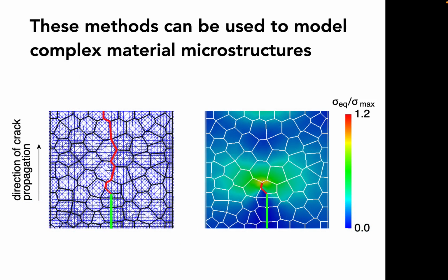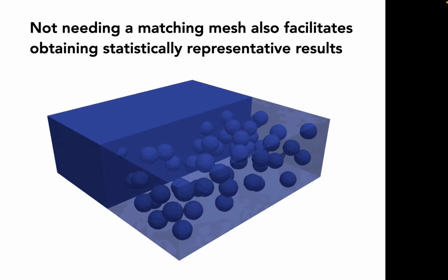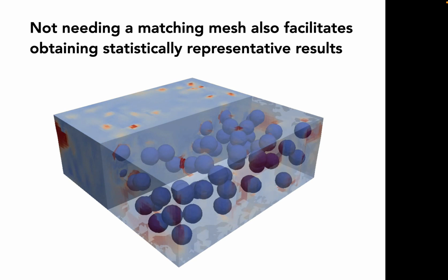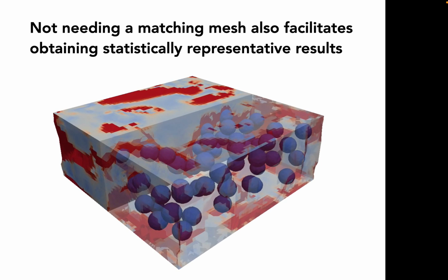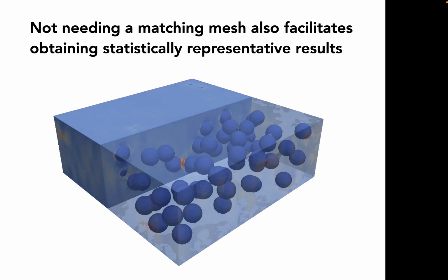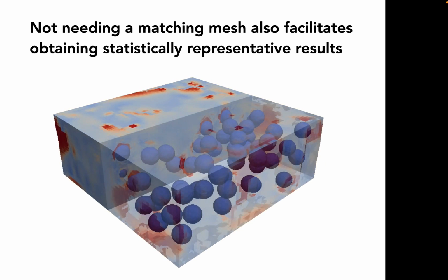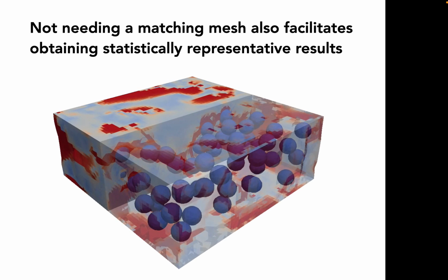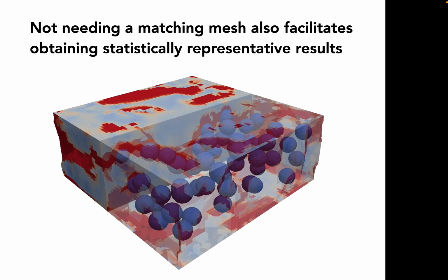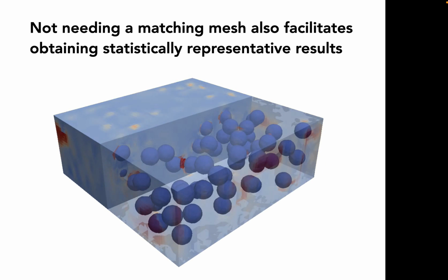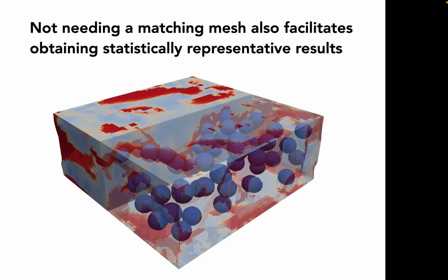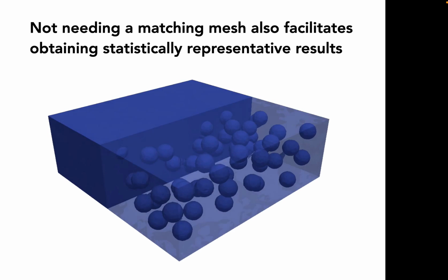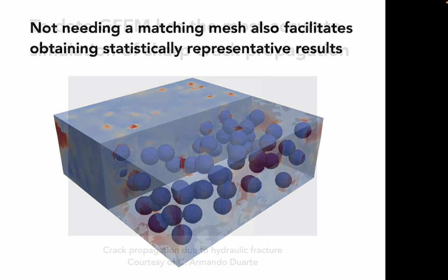Some problems on microstructures. Here you have a propagating crack. Then you have damage evolution in composites. Again, all those spherical particles are independent from the mesh. And here, what we're interested in is seeing what damage pattern is created by first applying an in-plane strain and then pulling in mode 1. So we're opening and then seeing where it should fracture, which is basically the red parts.